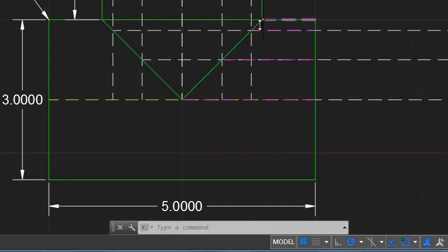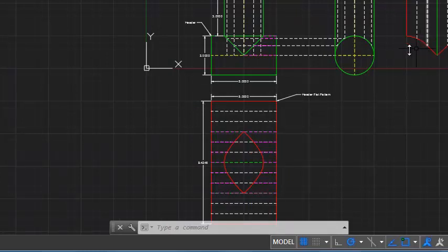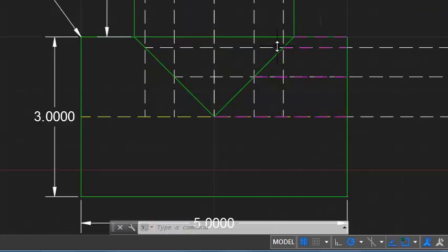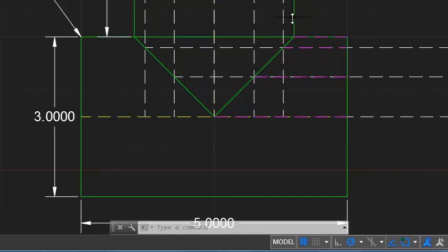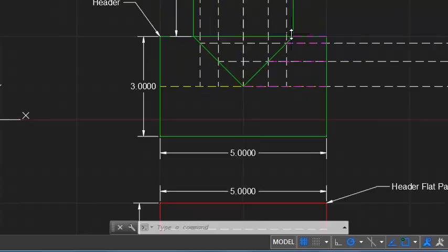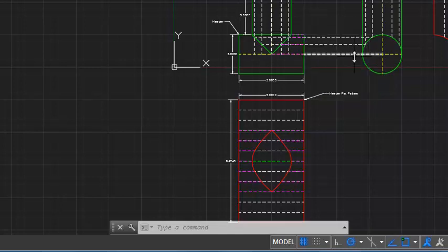So when that cuts out, this cutout is going to be to the OD of that branch, almost like the branch would be inserting into there. For something I wanted to line up on the ID, I would need to decide what thickness of tubing I'm working with and bring those ID dimensions down and use those as my development. That would make my IDs line up and maybe have tighter seams on the inside. So I have control over that. Maybe I need to be aware of what my application is.